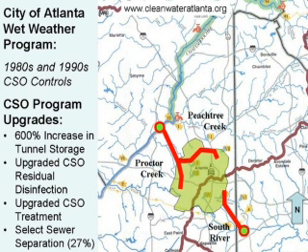Columbus, Georgia CSO facility involves screening, vortex separation, filtration, and chemical and UV disinfection. There's another project in Columbus. It's a stormwater treatment system. It involves flow control, screening, filtration, and UV disinfection. It was implemented to meet TMDL requirements, very similar to a CSO facility, and we'll talk something about it.